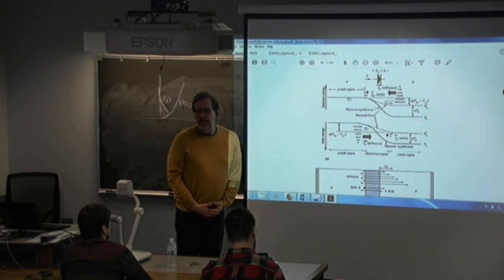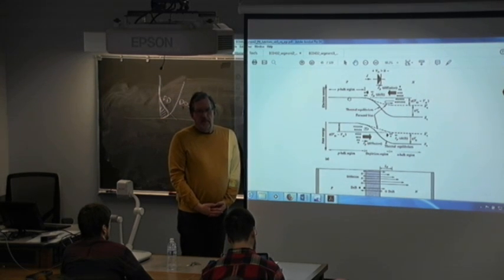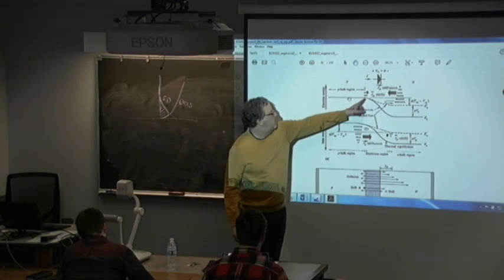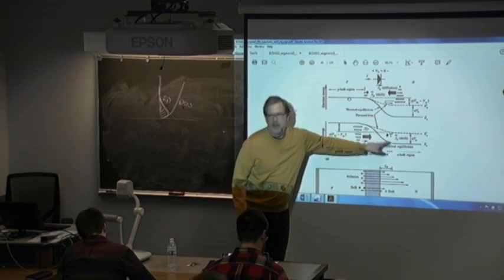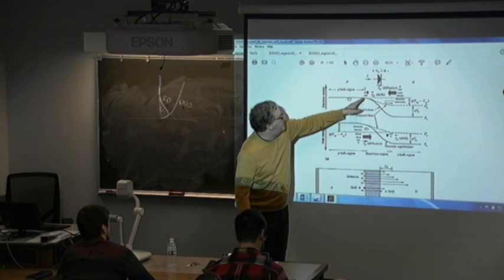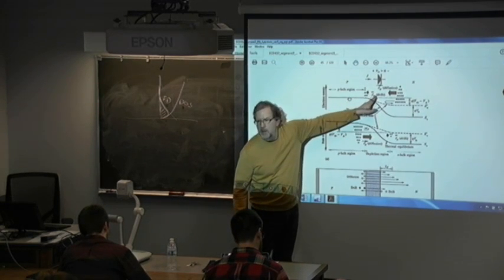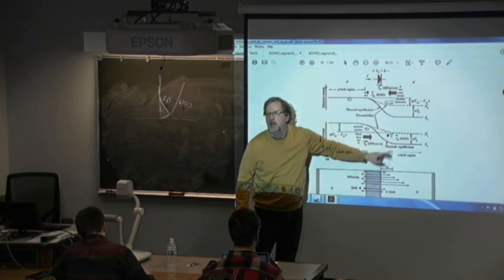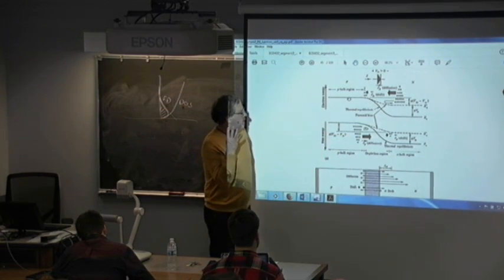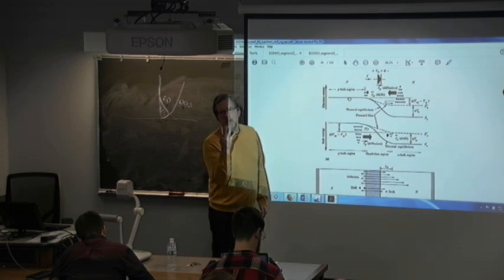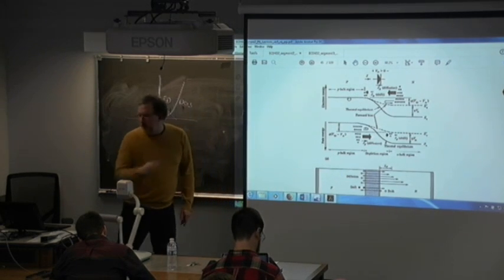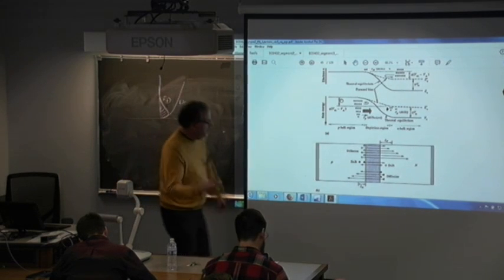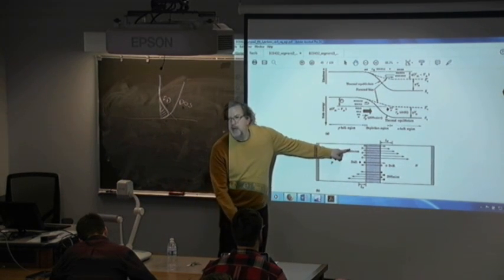Yes, sorry. I was just going to clarify. So generation in or near the depletion region is the rate limiting step for minority electrons? No, because it's a bipolar device. So it's the rate limiting step for the drift. So it's electrons on the p side and holes on the n side. Yeah, you have to tabulate 4 different carrier types. Two carrier types, but 4 different current components, which are illustrated right here, by the way.